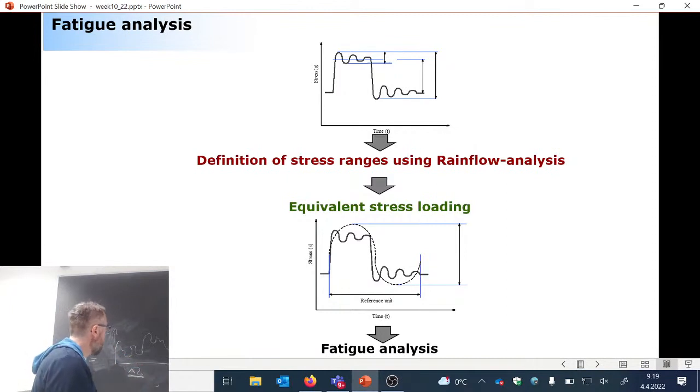Okay, so now you have this history shown like this. How much is the load put into the system and taken off? Because that combination you need to figure out. If you put a lot of load in your structure and you keep it there, that's not going to be too risky. But if you take your load and take it away, this kind of fluctuation is dangerous in terms of fatigue. How can you figure out this fluctuation based on the stress history like this? Well, you can use something called rainflow analysis.